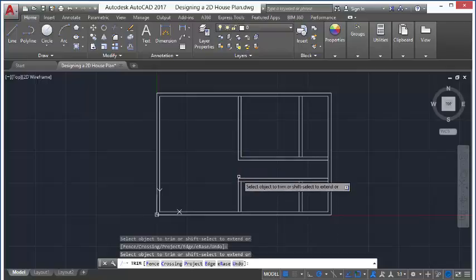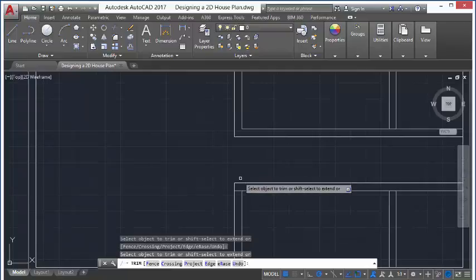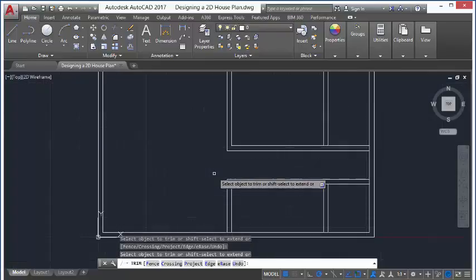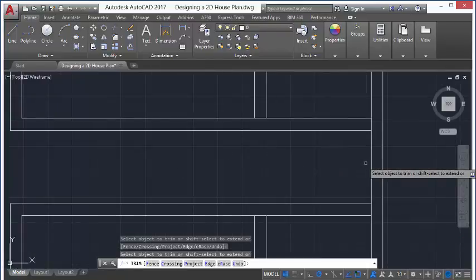and you can zoom in to see your drawing clearly. All you need to do is push your mouse wheel forward, then AutoCAD will zoom in. Clean up this guy. Now zoom out, position your mouse cursor and push the mouse wheel forward to zoom in. Now press the shift key and click this guy.